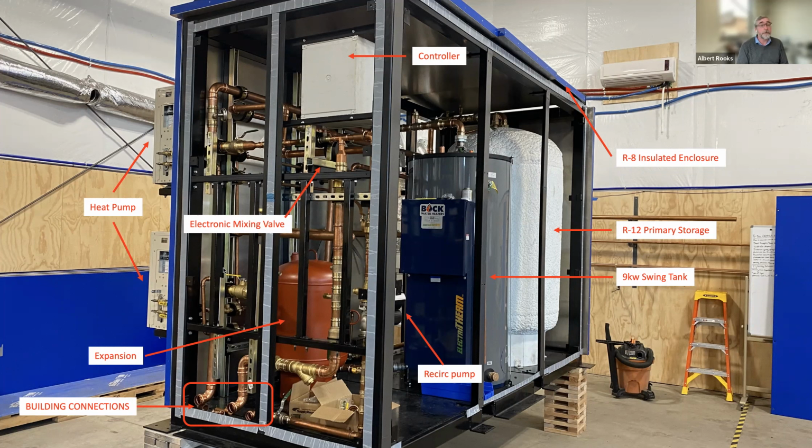Startup on a system, no matter whose system it is, it takes a day. You show up on site, you make sure the whole system's wet, start up the heat pumps, watch primary storage build. Depends on what kind of controller and visibility you have in the system. Watch primary storage get built up and then into the swing tank. Ideally, you've got a load. And if you've got a load, then you can start working with the temperature maintenance valve and things like this, and what is the interface to the controls.